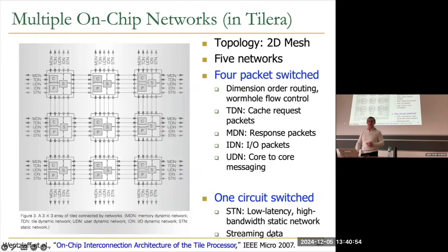And also we've discussed that they have circuit switch networks, which is really good for transferring a lot of data from one node to another node. If you're streaming from one core to memory, or from memory to another core, for example, if you have display traffic going from a GPU all the way to the graphics memory, then you may actually want to stream all of that huge amount of data through the network. To be able to stream data, you can set up a connection across a path, and you don't change that connection because you don't really need to dynamically switch every single packet, which is much smaller than the amount of data that you may be streaming.